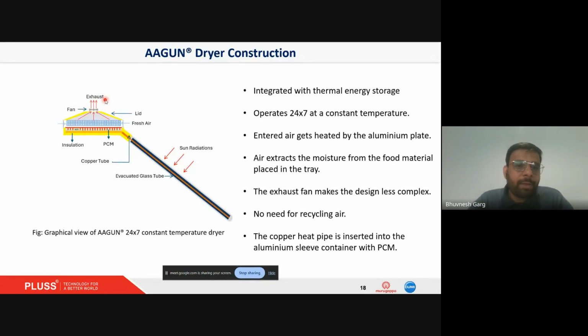So it is very important that you have these exhaust fans, forced circulation fans basically, which are running through solar panel. There is a small panel on one side of this hood, which is of capacity of 30 watt approximately, which is running your exhaust fan. In this whole construction, there is nowhere you need any grid electricity. The total solution is solar thermal energy and solar PV energy based. Yeah, so this is the concept basically.